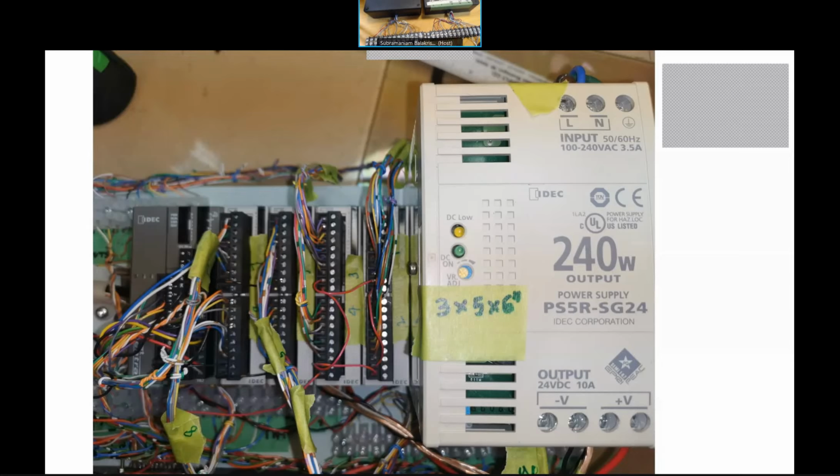The projects you're doing will not exceed 8 in and 8 out. So it is sufficient. This is the PLC that's controlling my robot cell. Then you can expand by banks of 16 inputs or 16 outputs. You've got to buy those modules separately and piggyback the master or mother unit. So in this case, it's got 32 ins and 32 outs in addition to the base 8 plus 8.